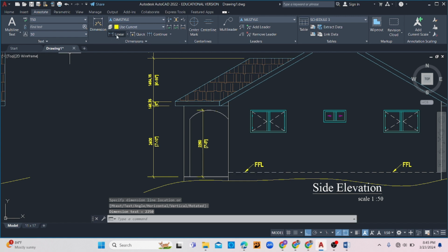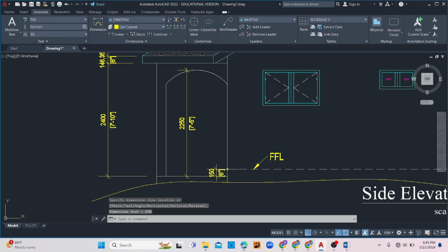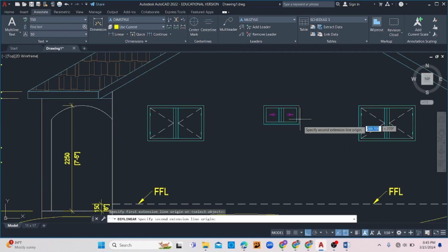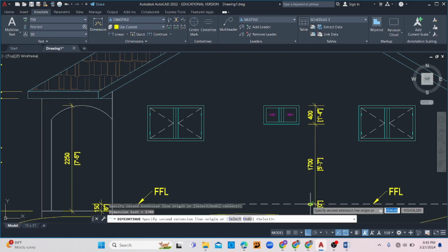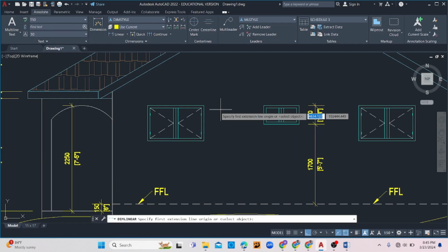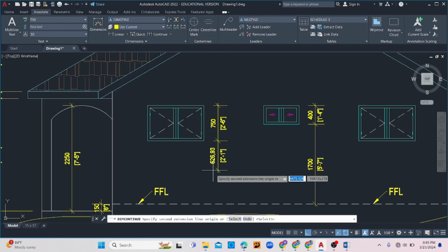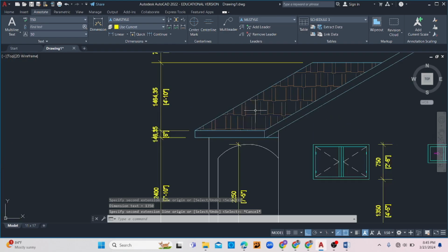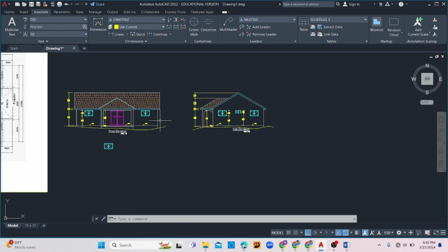We did capture the change in height or elevation for the ground between the veranda and the inside of the building. We can capture the height of this small bathroom window here and how far it is away from the ground level. Same treatment for height of these casement windows, how far they are away from the ground level. Alright, so those are some of the things. Once you have all of this in place, you're basically done and dusted. You're getting almost perfect marks for this.